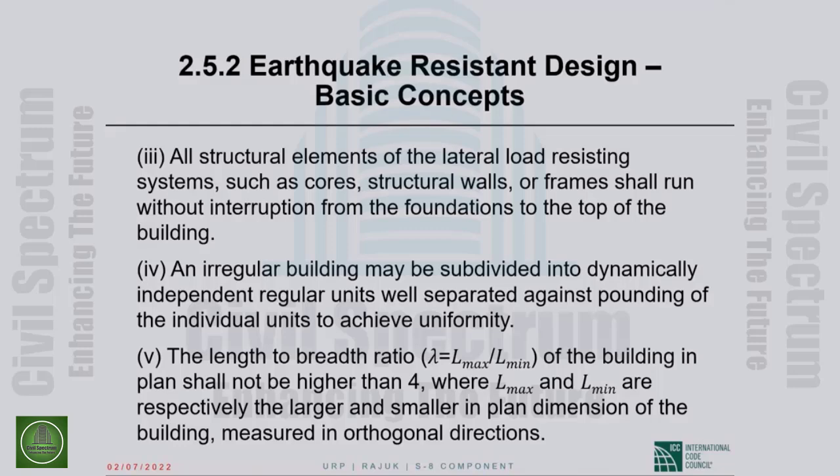So the shear walls in the upper portions of a building are discontinued as they come down for functional reasons, for commercial reasons. So yeah, however desirable it is, you don't always get the structural walls and frames running without interruption from the foundation to the top of the building. When they do, we are lucky. When they don't, we have to deal with that fact.